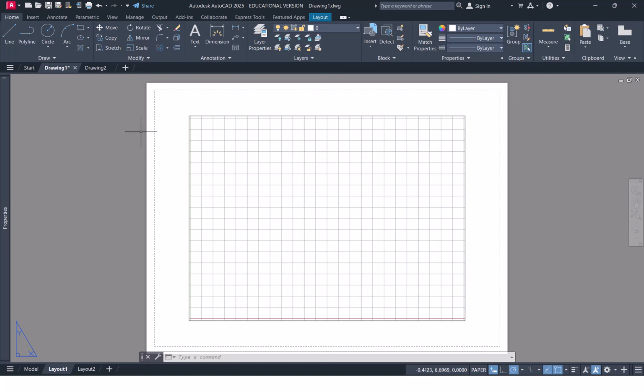Because in most mechanical drafting drawings that we'll be doing, you're either working at a 1-to-1 or a 1-to-2 scale. There's a little variation. There might be like a 1-to-4 or a 2-to-1, but most everything is 1-to-1 or 1-to-2. It makes it easier to deal with your text height and dimension height if you do all of those things in paper space, because then you're just doing it full size.